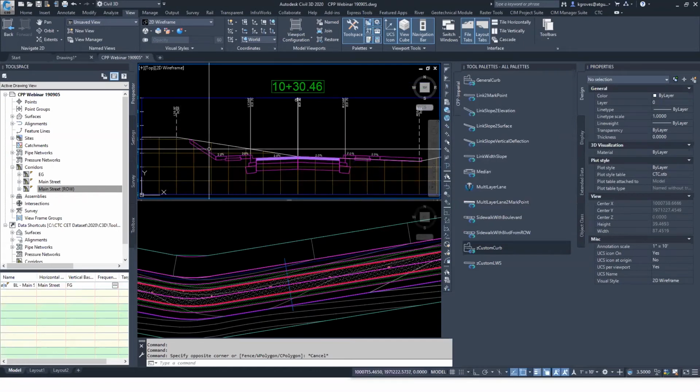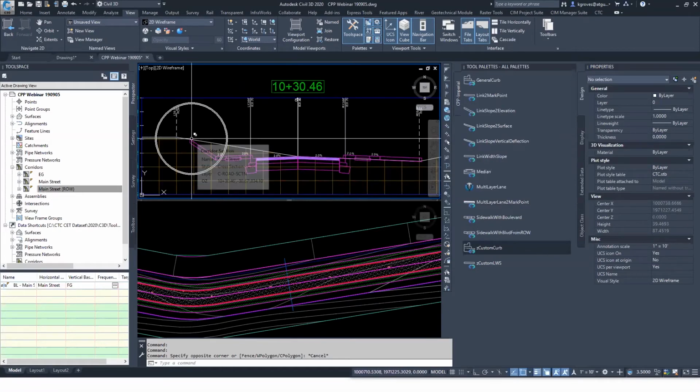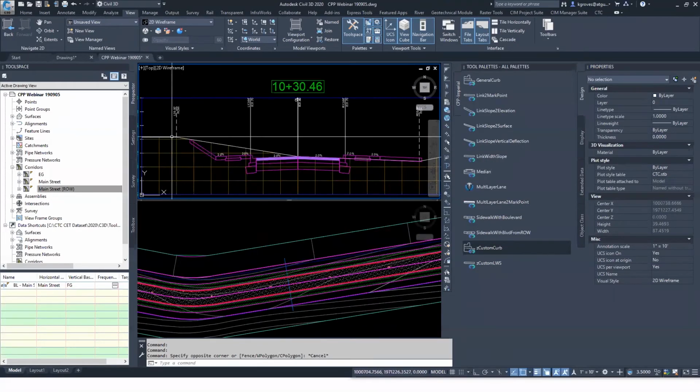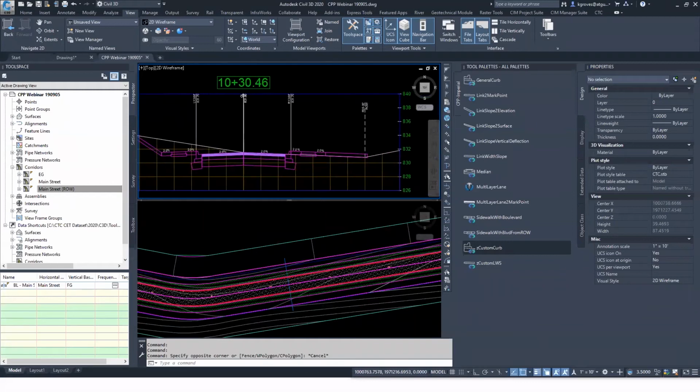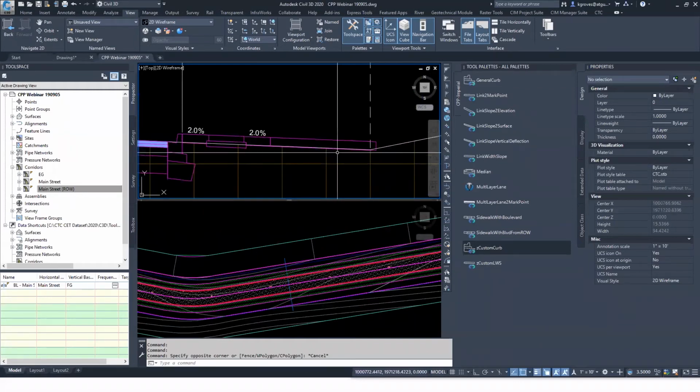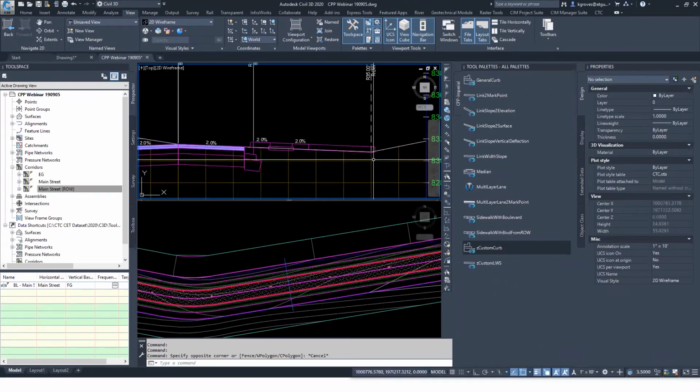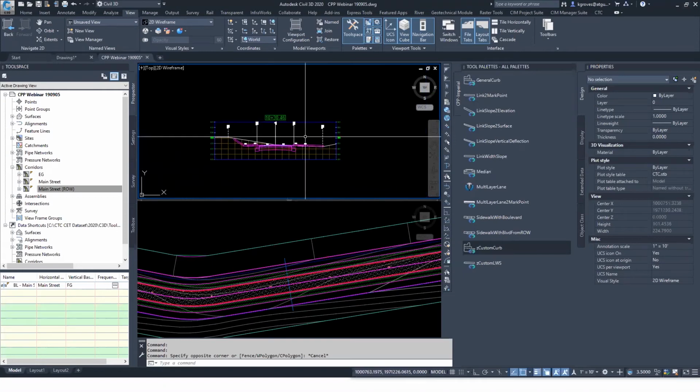And the reason why I'm using a second corridor is because I don't necessarily want to be tied directly to that beginning one. And with this, I can see I'm inside on my surface target, inside the right-of-way on the left side, but now I'm outside of my right-of-way for the right side of my road, and I need to go back and reconfigure my design. So with that, that sums up where I wanted to go today.